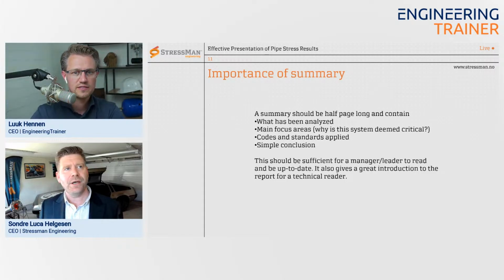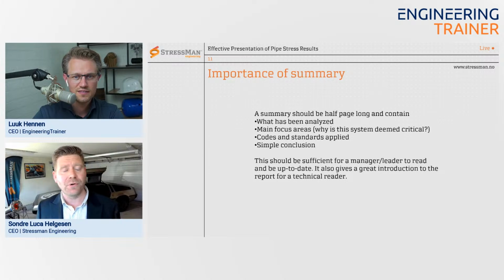I feel, well, it depends. Depending on the size of your components, your thicknesses, and so forth. We've been doing a lot of FEA with respect to high pressures. For example, if you are in Chapter 9 of B31.3, there are requirements to do more comprehensive fatigue analysis.